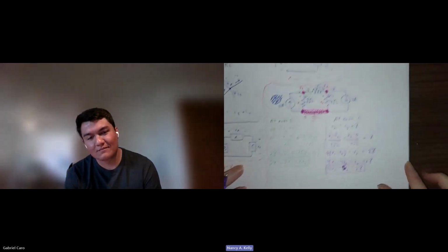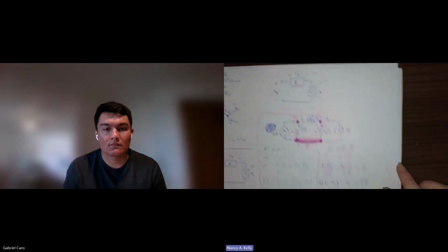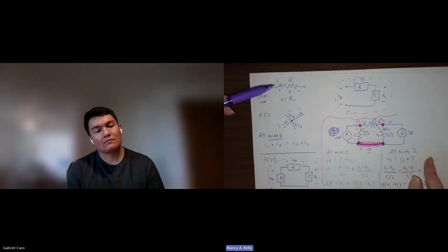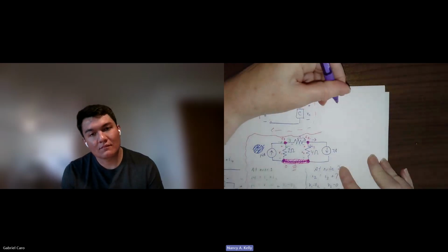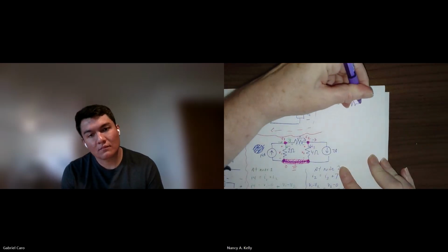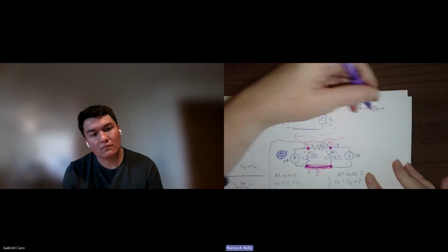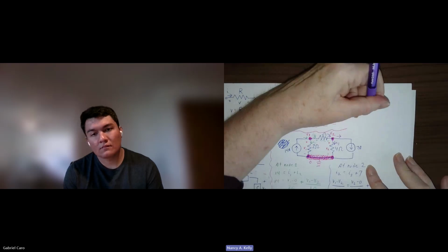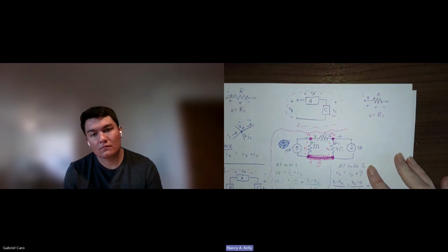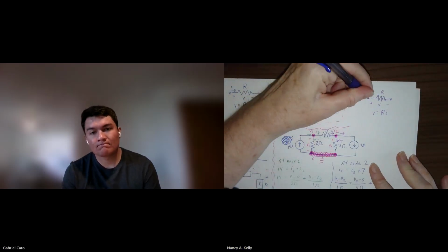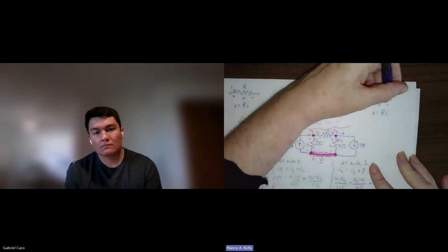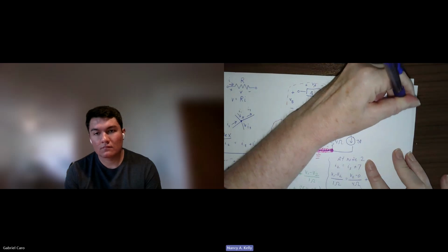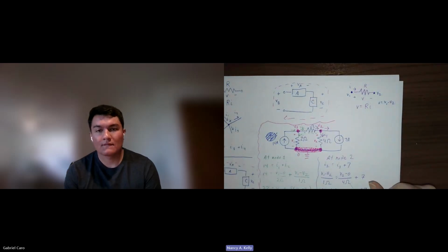Now, I want to go back because I realized I didn't explain this particularly well. This business up here of Ohm's law. If I just redraw this over here and put in those circles like I had here, I have my voltage V, and I have I coming in, and here's R. I told you that Ohm's law says V equals RI. If I label this as V1 and this as V2, then this voltage V is equal to V1 minus V2. That's what I'm basing this on.